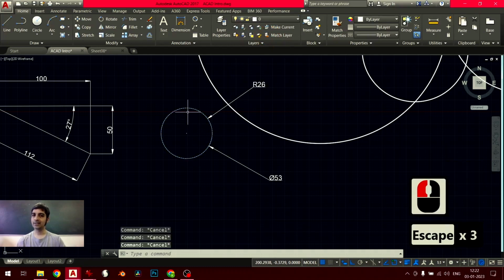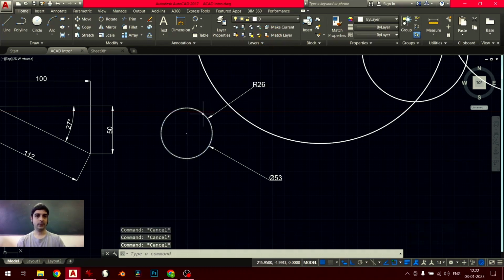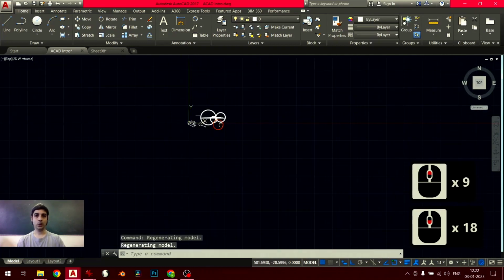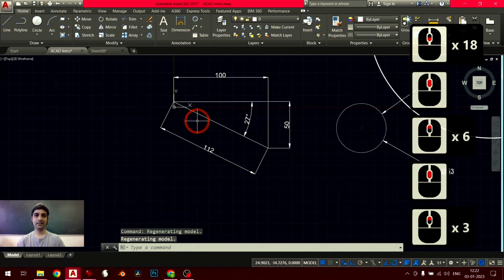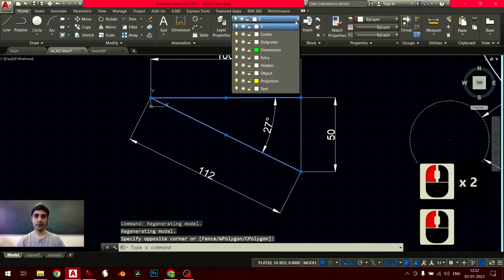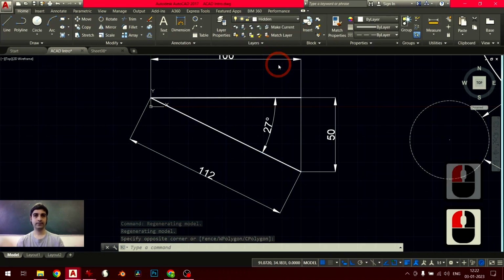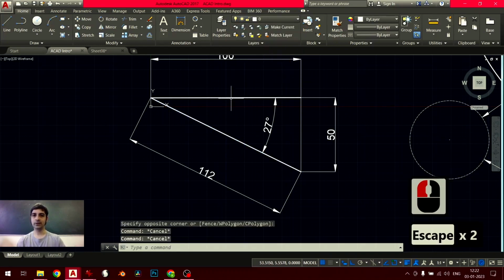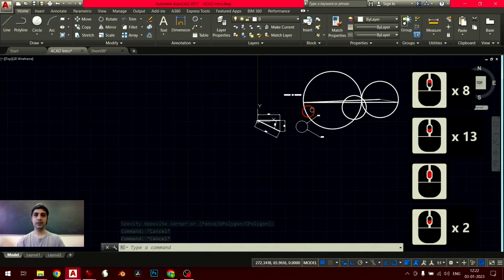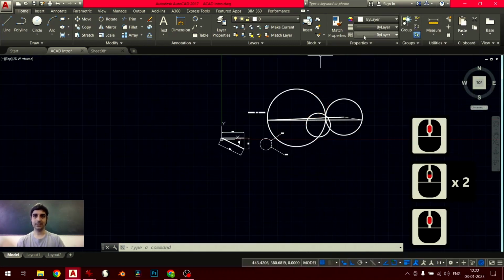Now I'm not sure if you can see if anything has changed, right? If I zoom in, you'll see the line type is being applied along the same lines. Let's say these are supposed to be hidden lines and they belong on the layer called hidden, which has the dashed line type applied. Again, you can't see much of a difference until you zoom in. So that's happening because the default line type scale in AutoCAD is pretty low.